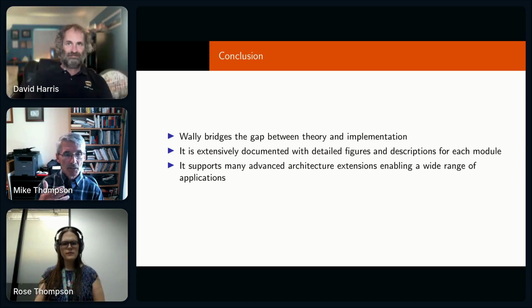Sometimes it's justified. Sometimes it makes sense to add a custom instruction, but I would really encourage people who are excited about adding custom instructions to really think about why they want to do that before they go to that effort, because it's not trivial. The problem only gets bigger when you solve the RTL problem, when you implement the instruction and get it to work and not break the core that you've already got working. Now the real work begins. It's really hard to support custom instructions. And in case you're wondering, yes, this is the voice of bitter experience.